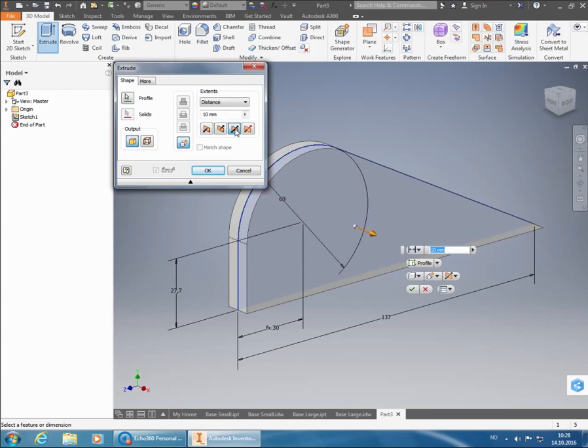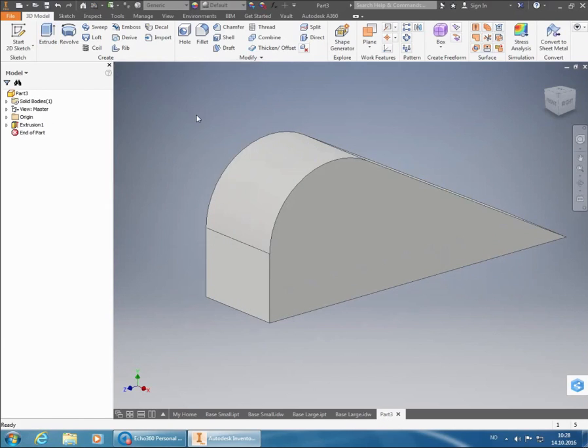so it's going to extrude it an equal length on both sides. The dimension that we are going to give is the total width that we are going to extrude it, but it's going to do it equally on both sides. So basically we're creating a symmetry plane in the middle of it. And this one is going to be 35 millimeters thick. Then we click OK.